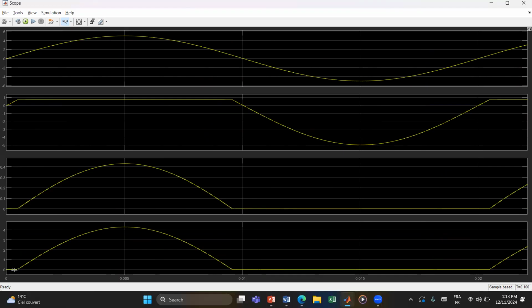It equals zero because the diode will not let the current pass until the input voltage equals the value of the forward voltage, which is 0.7. If we take, for example, the value 0.7 until this point,